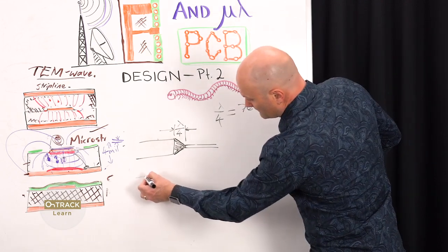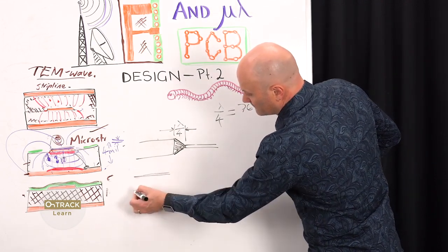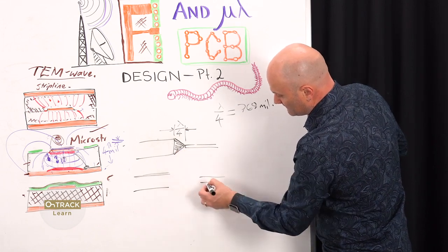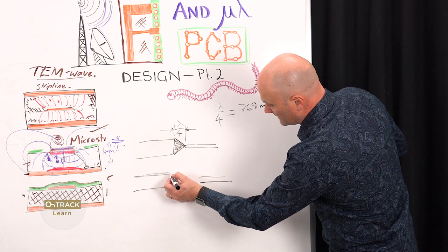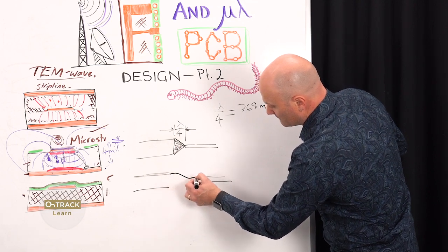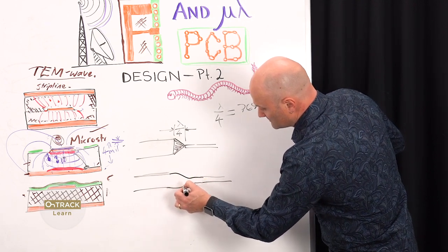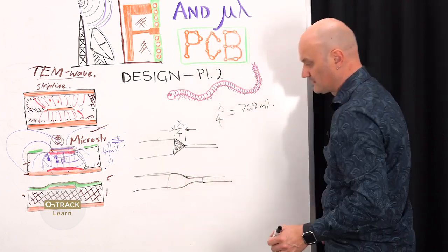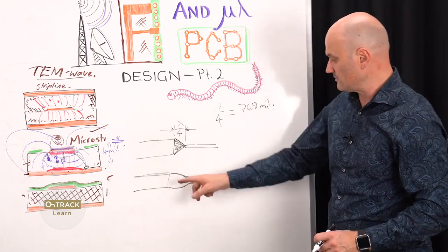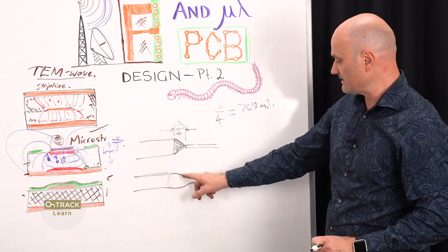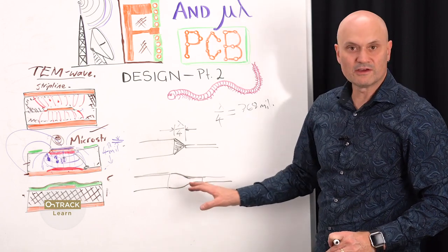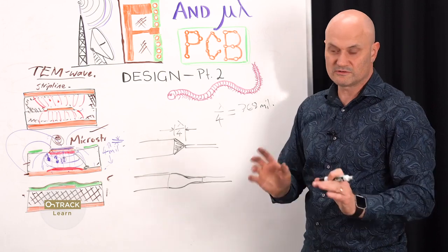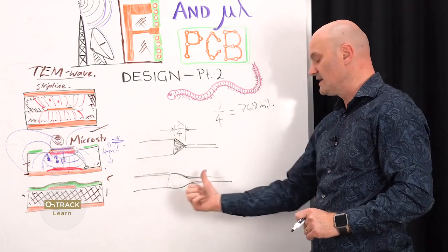There are even better scenarios, and there are calculators you can find at Microwaves 101, where instead of having a hard taper like that, they've found an even more optimal approach is to have a polynomial curve. It's a very slight curve. You can almost not see it in the final design, but there's an Excel spreadsheet you can download from there that will allow you to calculate the characteristics of that curve based on your target, and that gives zero reflection back to the source, which is good. That's a good thing. You want all your energy to go to the load.